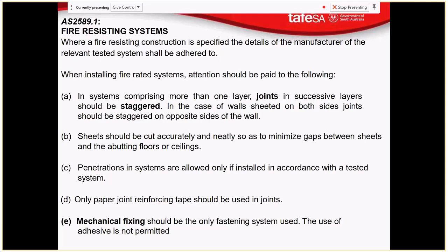Another detail that you'll typically see in the fire-rated walls: the studs like this, insulation between those studs, and then our layers of fire-rated plasterboard there, like that, and then continue on, like the stud here, and the stud there, for example. Or we'll have a staggered stud scenario.